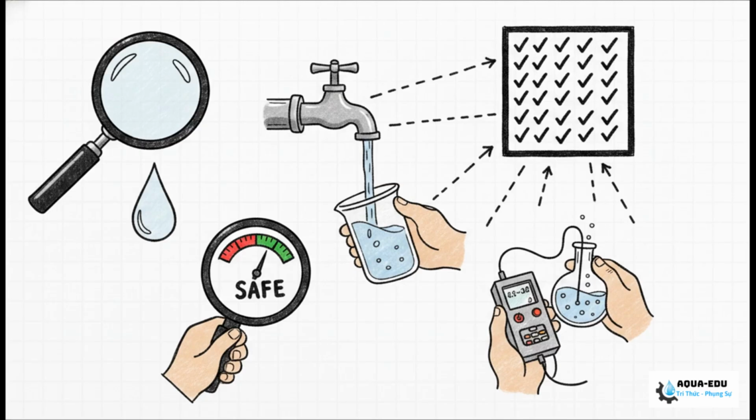You need to verify that feed water hardness is virtually at 0. You've got to check your RO permeate quality for any kind of degradation. Confirm that your feed water silica is strictly under 0.5 parts per million. And grab a fresh measurement of your incoming CO2 levels.